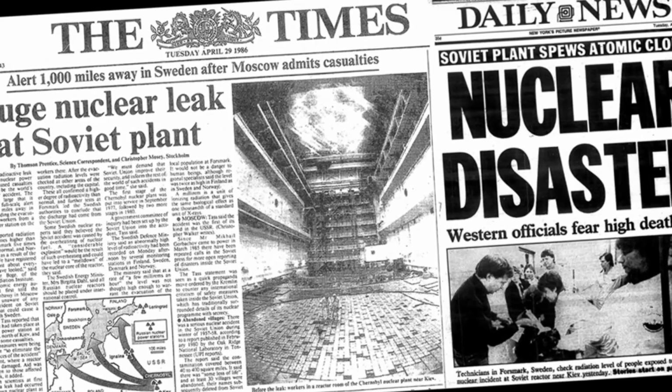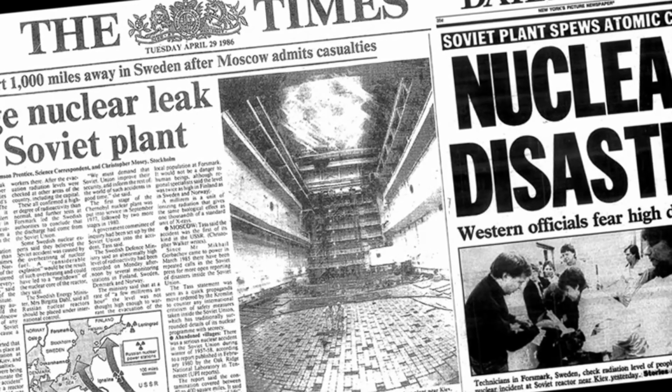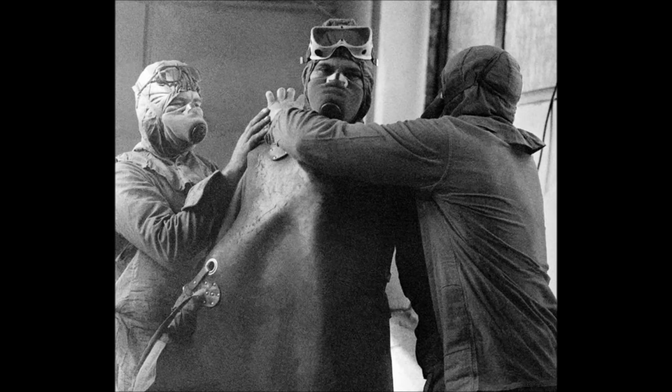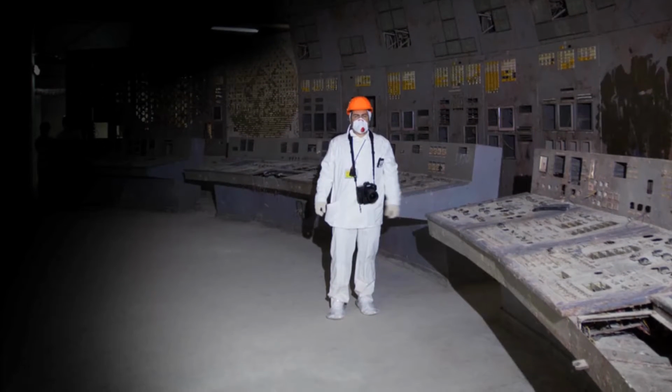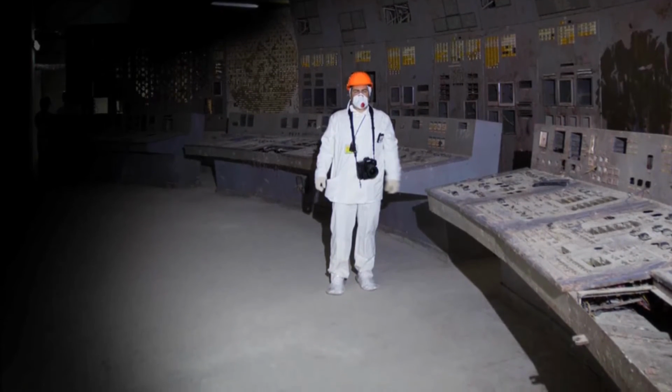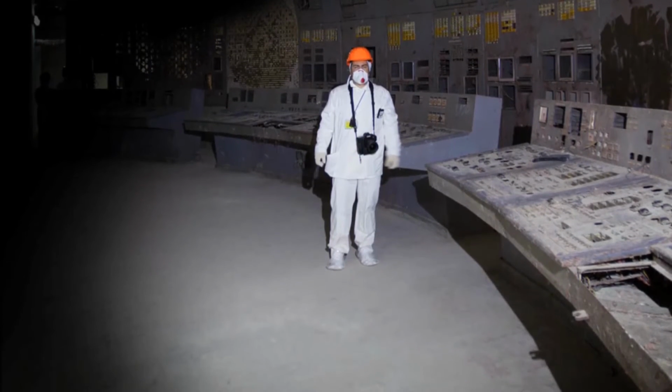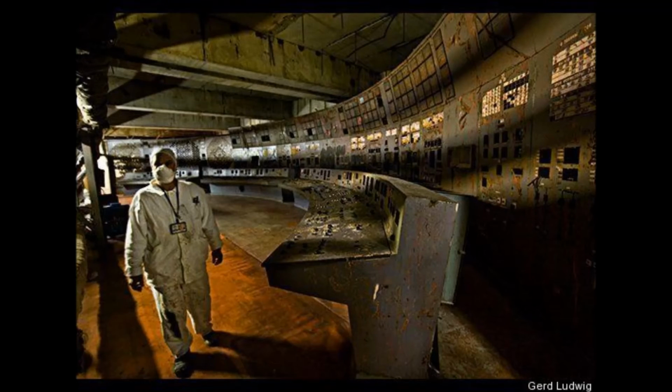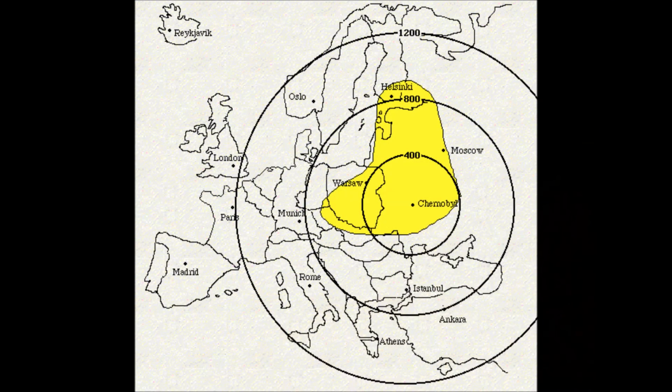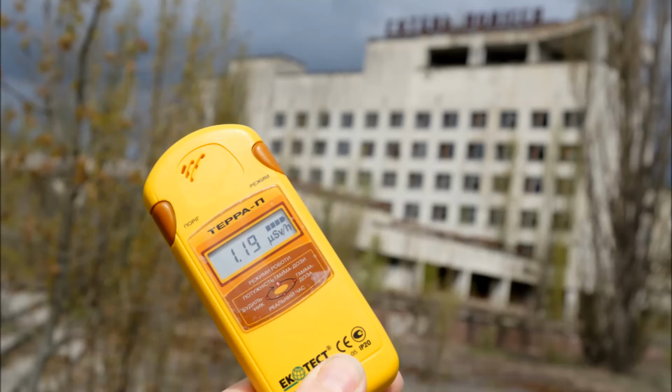The Chernobyl nuclear disaster could have had a lot less probability of occurring, all because the operators ran the plant at very low power, without adequate safety precautions, and without properly coordinating or communicating the procedure with safety personnel. The reactors also were highly unstable at low power, primarily owing to control rod design and positive void coefficient, factors that accelerated the nuclear chain reaction and power output if the reactors lost cooling water. These factors all contributed to an uncontrollable power surge that led to Chernobyl's destruction.